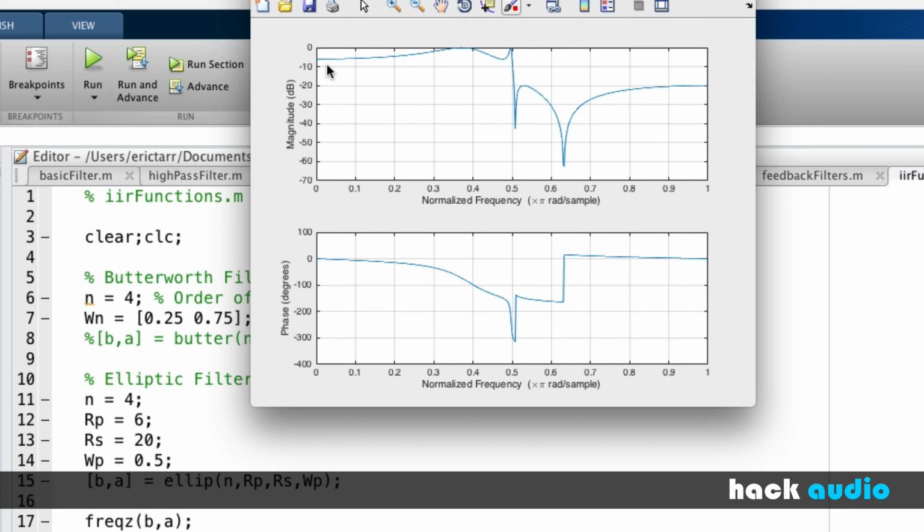So there's a lot going on in this plot, but we have our cutoff frequency. That's the point to pay attention to over here first. At our cutoff frequency, we have a very sharp slope that goes between our pass band over here and then our stop band. First thing to notice is that our stop band never goes above 20 dB of attenuation.